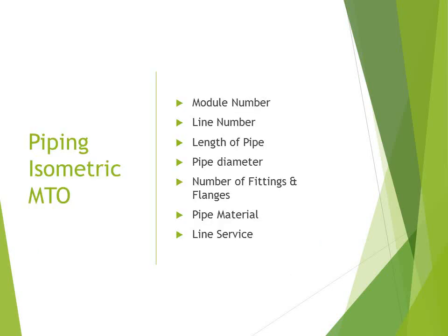The piping isometric MTO contains a lot of useful information and can easily be grouped by module. Information includes line numbers, total length and size of pipe for each line number, total number of fittings such as elbows, T's, reducers, etc., the pipe material and the service of the lines, such as hydrocarbon, non-hydrocarbon, liquid or gas, etc. If module size was included in the dataset, information about piping density or complexity could be derived, which may improve the model. For our purposes, to keep things simple, the focus is on the length of pipe for each module.